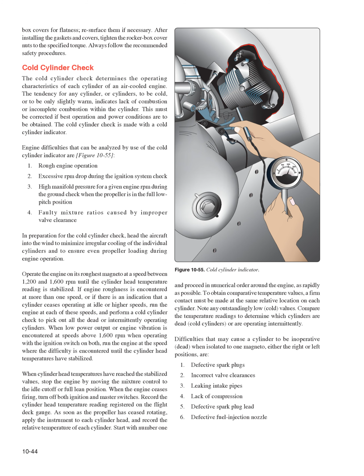Cold cylinder check. The cold cylinder check determines the operating characteristics of each cylinder of an air-cooled engine. The tendency for any cylinder, or cylinders, to be cold, or to be only slightly warm, indicates lack of combustion or incomplete combustion within the cylinder. This must be corrected if best operation and power conditions are to be obtained. The cold cylinder check is made with a cold cylinder indicator. Engine difficulties that can be analyzed by use of the cold cylinder indicator are: (Figure 1055-1)